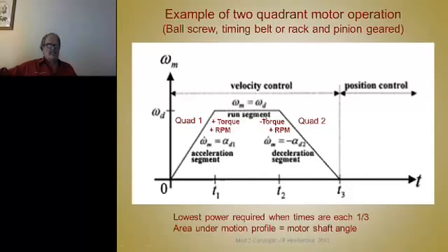And of course, when you accelerate, you overshoot, so you're going to have some settling time there. When you stop, all of a sudden you've got a big inertial load, you're going to overshoot. You'll get some ringing due to the compliance. So you might need damping in the circuit, which is friction. All those things taken into account. But this type of move demonstrates the importance of positive and negative torque. Negative torque is always braking torque.